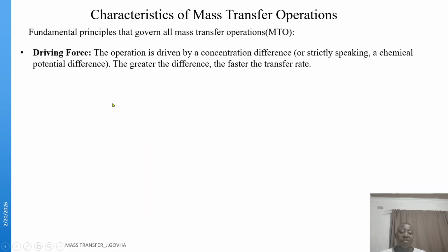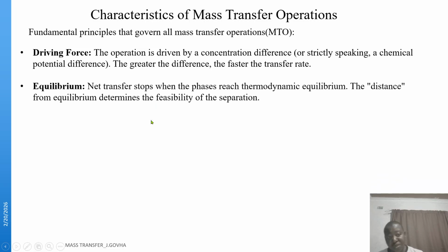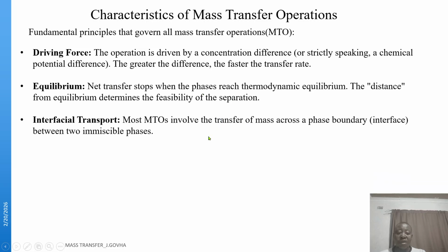So the fundamental principles which govern mass transfer operation are your driving force, which we have already talked about. The greater the difference, the faster the transfer. Then equilibrium, the net transfer stops when phases reach thermodynamic equilibrium.